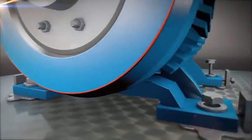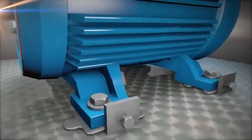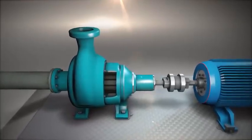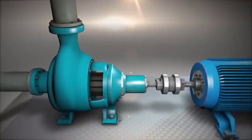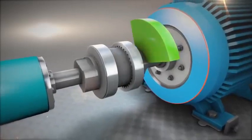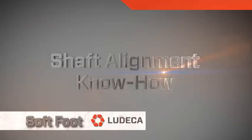Likewise, all pipe fitting should be completed without imposing any stress on the machines. When machinery is properly installed and given reasonable maintenance, the asset's operating life should meet or exceed its life expectancy. A precision alignment of the machines to proper tolerances is required before releasing the asset to operations and be put in service.